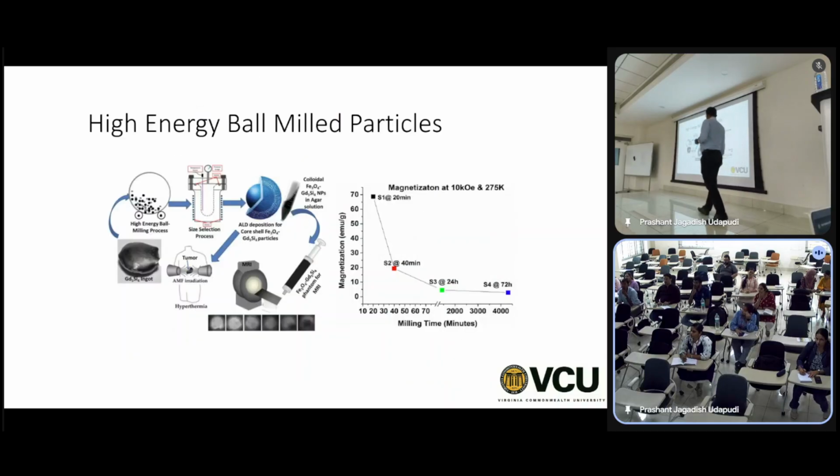So now, what do we want to do? We want to first make powder of it, right? To make powder, first you have to make the material, gadolinium silicide ingot. Basically put gadolinium and silicon, heat it up to 2500 or 2600 degrees, that is the melting point of gadolinium, and silicon has a slightly lower one. So when you heat it up, both become liquid.